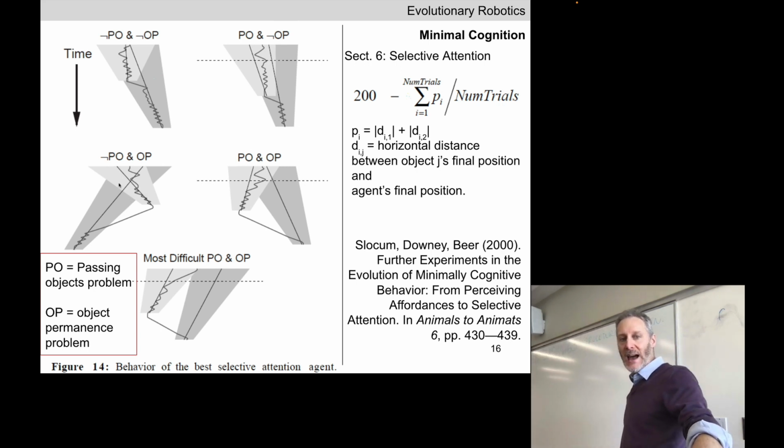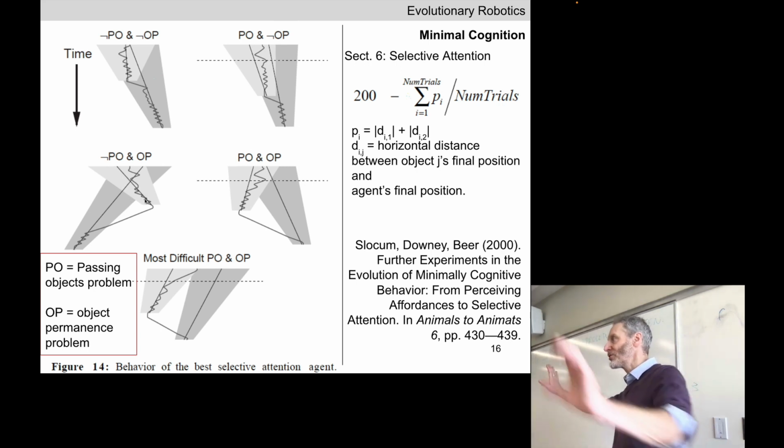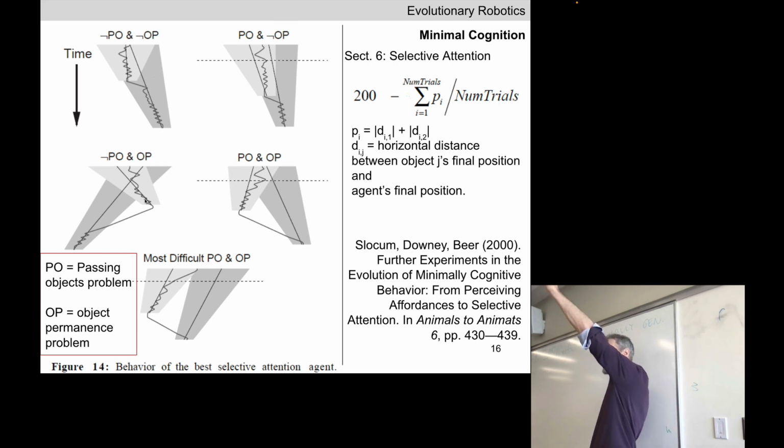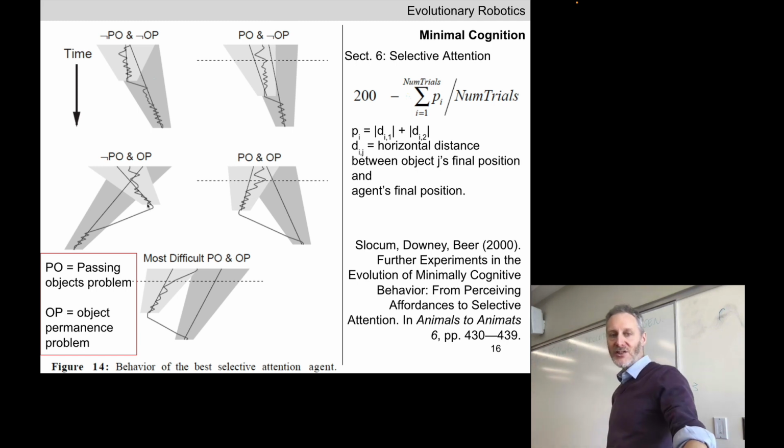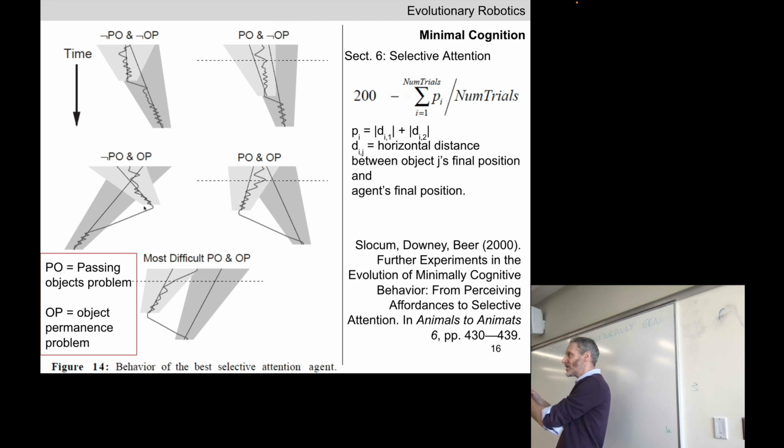And at some point, as the robot is moving further and further to the right, the second object, which is falling more slowly and is going to hit later, represented by the darker polygon, the robot moves so far to the right that the robot's leftmost proximity sensor is no longer sweeping along the underside of that second object. It can no longer see it, and it can no longer see it from this time until this short time later when it actually catches the first object.